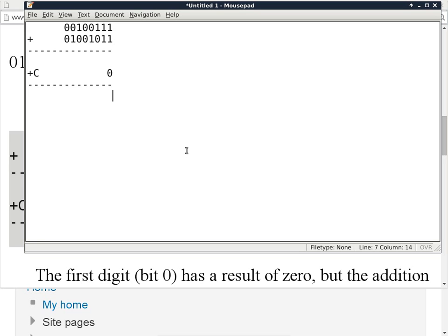All right. So the way I do this is not exactly the same way that you learned to write out addition in school, because I use one entire row to represent the carry bit from the previous digit. Let me identify which row I'm talking about here. I'm using this row to represent the carry bit from the less significant digit. Usually it is not represented like this, but I would like to do it this way because then it becomes clear why the mechanism that we'll talk about next is called a half adder.